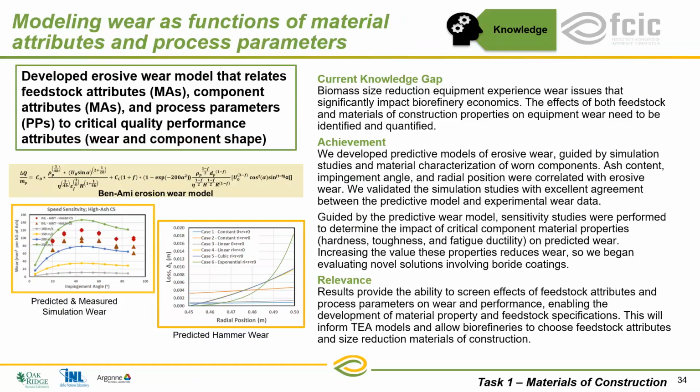So in this work, researchers from this task took a very well-understood, very well-accepted erosive wear model and were able to predict the data coming from an accelerated wear testing facility or piece of equipment, so that we can capture both the influence of the material of construction, but also the biomass material, the inorganic species, and actually the geometry of how the wear was done.